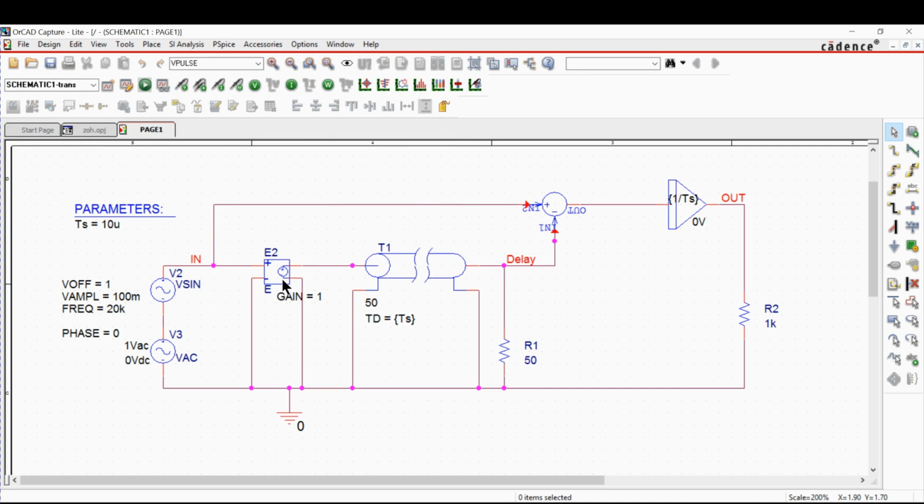If the system calculates the steady state situation at 0 time, then if there is 1 volt here, it'll calculate 1 volt here, because this is the stable, static situation at 0 time. However, in the real run, this value here is 0, because at 0 time you have only this part coming in, and since no time has passed, this is still 0.